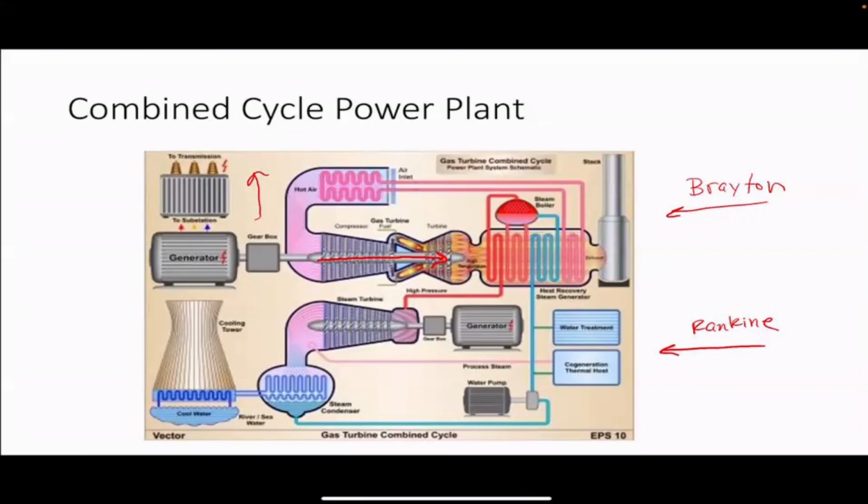But leaving a jet engine, the effluent is extremely hot. In fact, when we solved a couple problems related to the Brayton cycle, that can be at hundreds of degrees C. And oftentimes you just let that go into the atmosphere. Well, instead, if you ran a Brayton cycle, one of the things that you could do is use that exhaust as the boiler for a Rankine cycle. And you'll see that's exactly what's happening here.